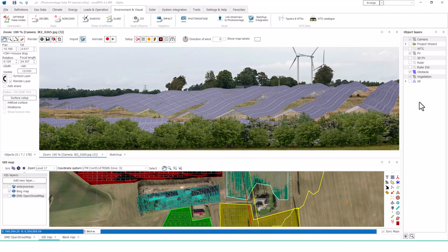Again, it is hopeless to solve using the rubber tool or Photoshop, so here the auto erase feature comes into play. What it does is that it hides everything that is behind the digital elevation model, and that is just what we need in this situation. Unfortunately, it also slows down the rendering process significantly, but there are a couple of things we can do about it.